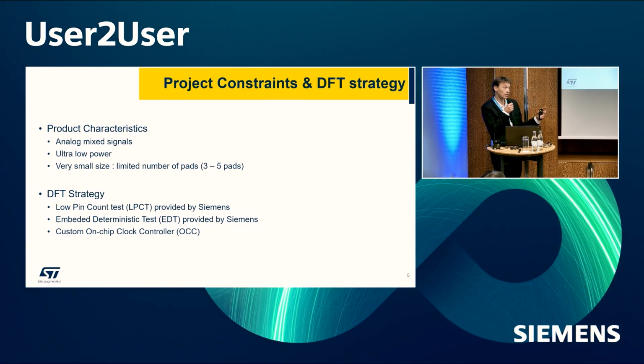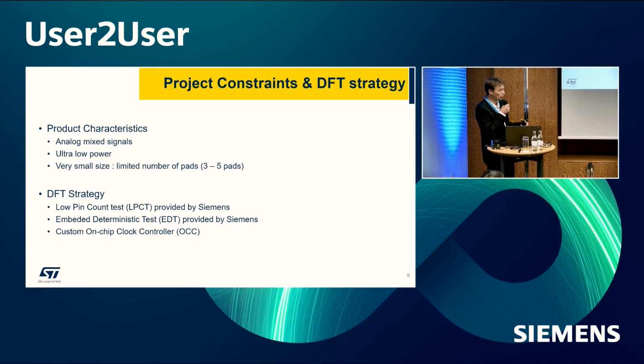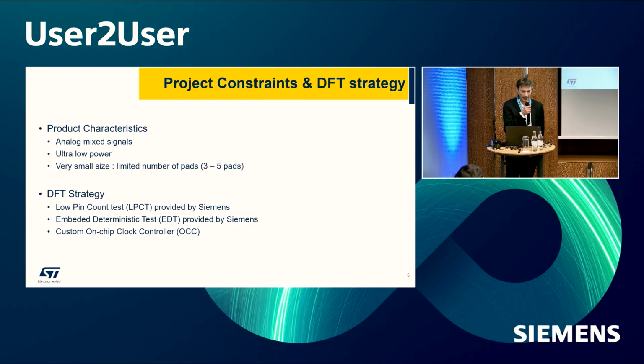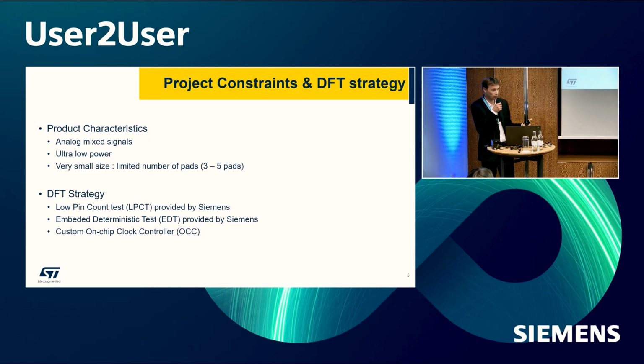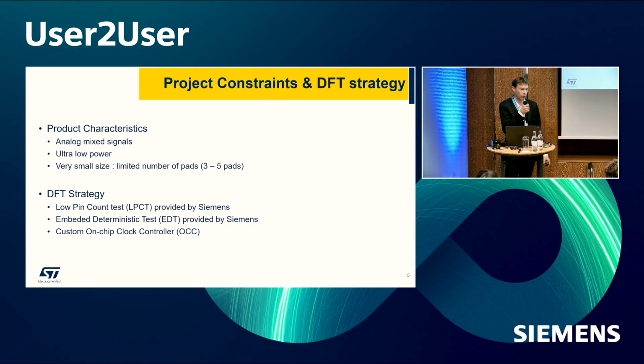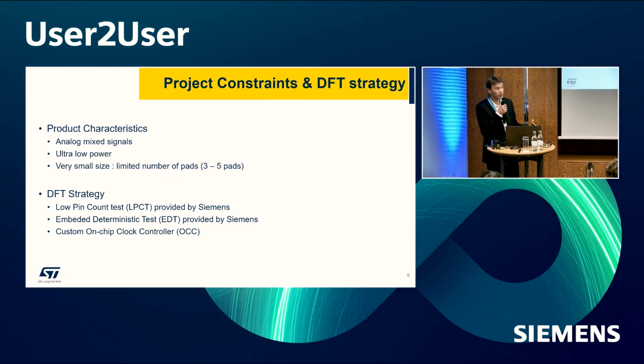Usually they use the functional pads to apply the scan data and do all their manufacturing tests. So what they typically do is use I2C as a mechanism to configure all their devices, and then the last sequence of I2C lets them turn their I/Os into test I/Os, or I/Os used for the manufacturing test. So this brings a couple of challenges.